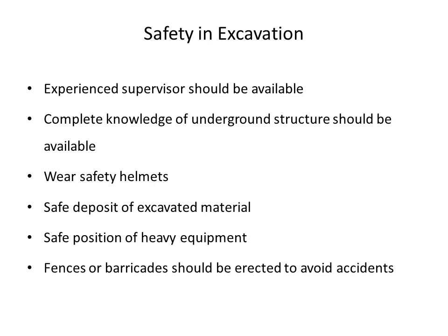Then once we are excavating a trench, it should be kept away from the public, and we should place proper fences, barricades, etc. to avoid accidents from people falling into the trench. That is, at all places where the public is likely to trespass, we have to place proper fences and barricades to avoid accidents. So these are the concerns in safety in excavation.